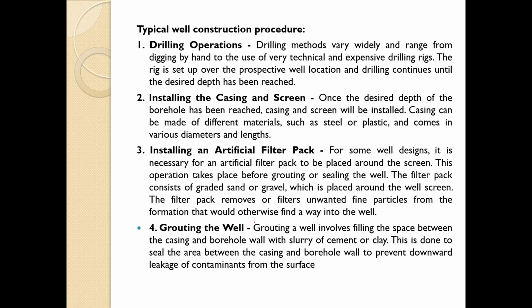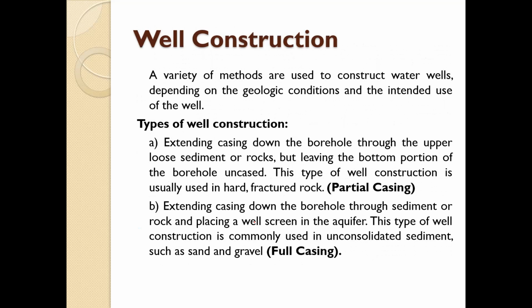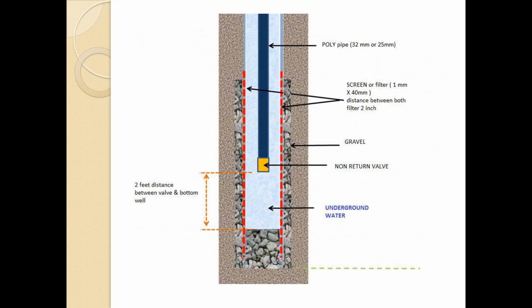The filter pack consists of graded sand or gravel which is placed around the well screen, and the filter pack filters out unwanted fine particles from the formation that would otherwise find their way into the well. As we can see here, this is the filter pack.